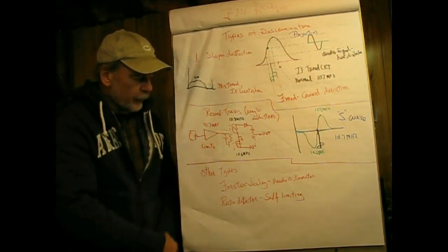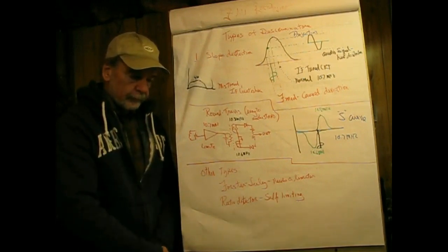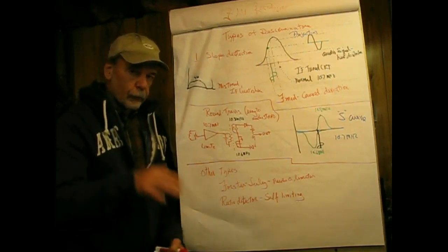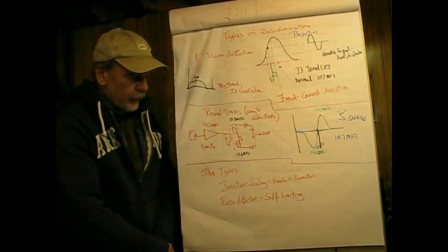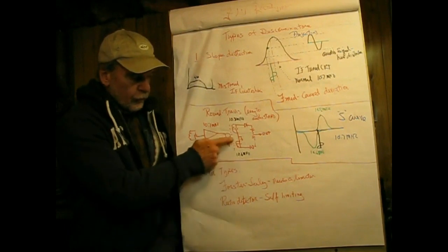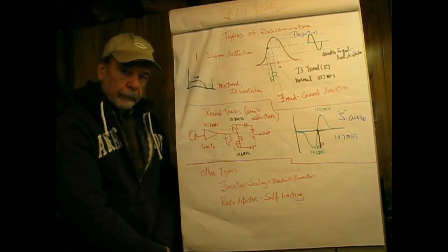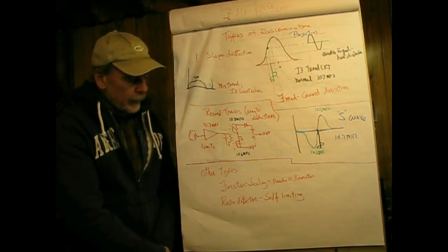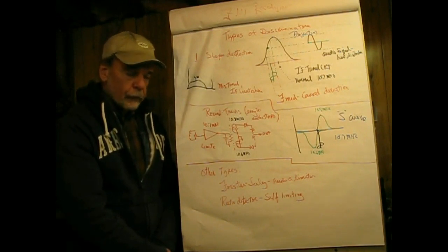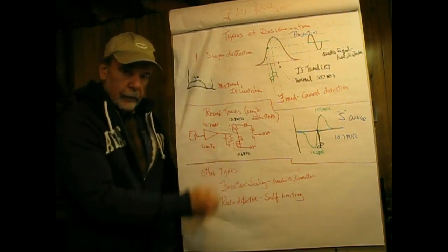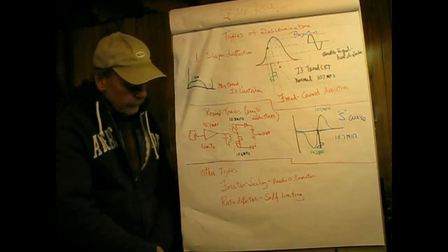I worked on a frequency modulated microwave for voice transmission, a lot of voices, 600 channels as a matter of fact, and it had one of these guys, and part of the lineup procedure was to tune this within 2% linearity. And I had a lot of trouble, and I was new on the job, and then I read the instructions. The AFC was turned on. So every time I make an adjustment here, it would shift the local oscillator. There's a message in there somewhere about instructions.